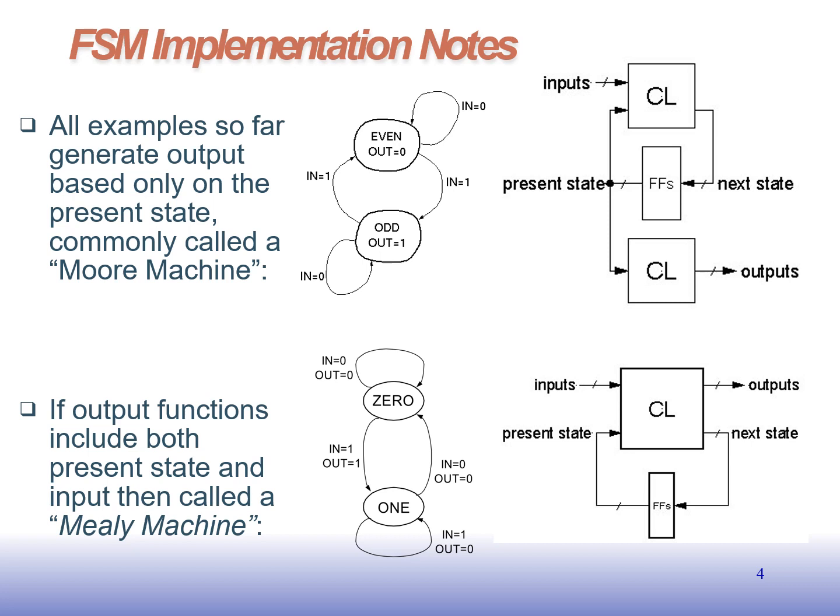There is a state, and the state can be stored in flip-flops as the present state and the next state. The input is given to the combinational logic block, and depending on the present and next state, it delivers the outputs. So this is the structure of the Moore machine.